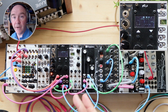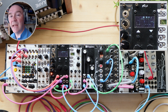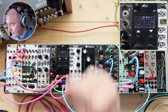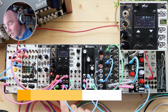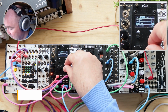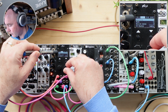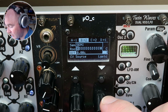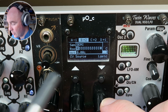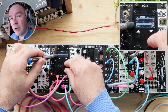Now, if we can quantize voltages into voltage ranges, we can also quantize them to basically an on and off range, in other words, a trigger. Let's look at using a quantiser as a trigger source so that we can trigger other events in this patch. Now, we have one spare quantiser left here, quantiser B, and what I'm going to do is go into it and set it to semitone mode. And I'm just going to adjust the active scale map to have one note only, so it'll only quantize to one note.